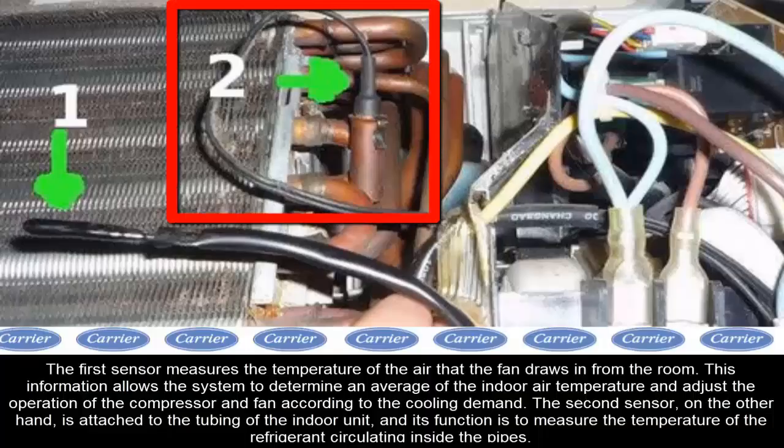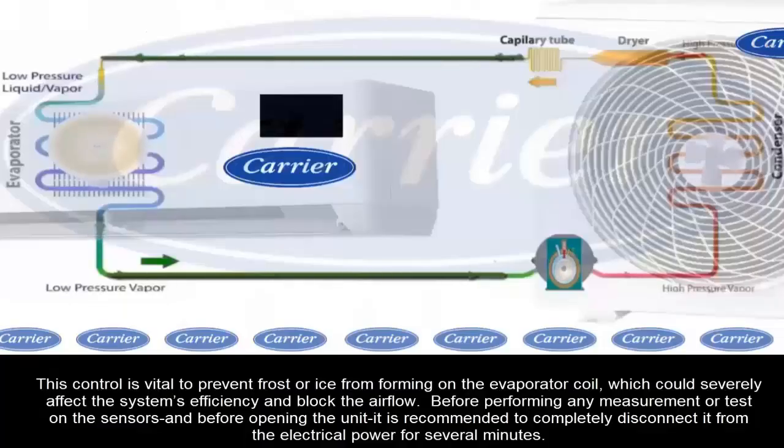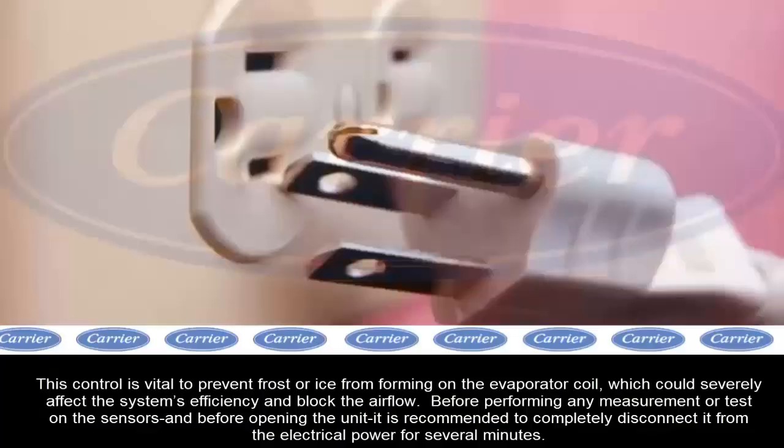The second sensor, on the other hand, is attached to the tubing of the indoor unit, and its function is to measure the temperature of the refrigerant circulating inside the pipes. This control is vital to prevent frost or ice from forming on the evaporator coil, which could severely affect system efficiency and obstruct airflow.